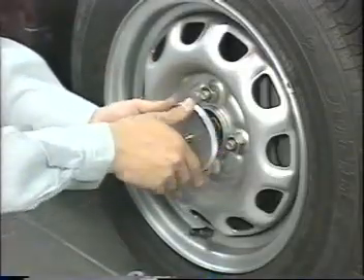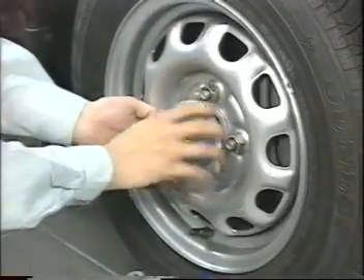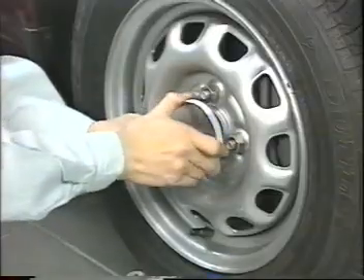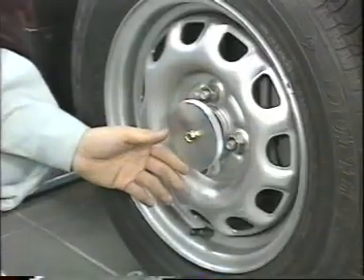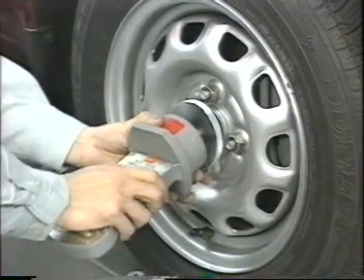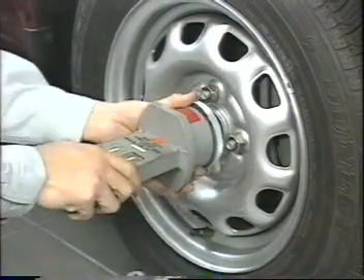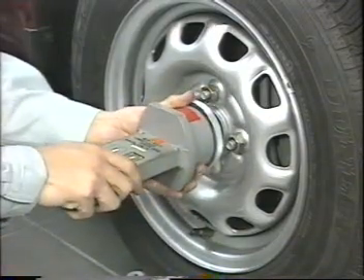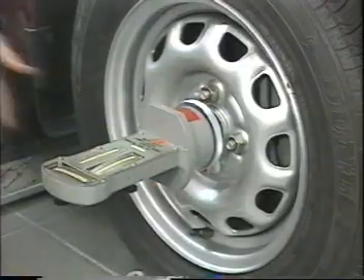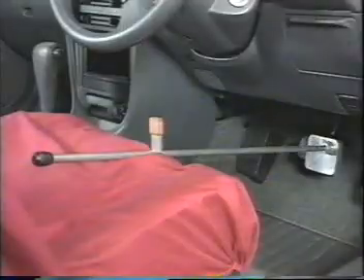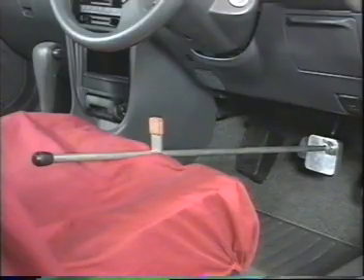Then fully tighten the gauge adapter by hand. And attach the camber caster kingpin gauge. The inspection should be carried out with the vehicle empty and the front wheels locked, so depress the foot brake using a brake pedal pusher.